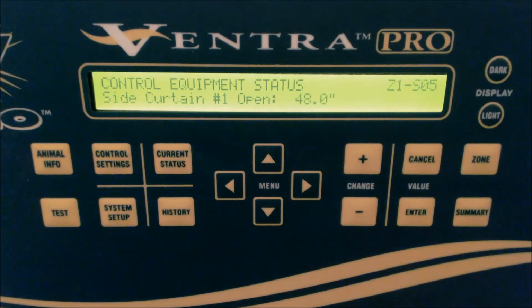The best way to prevent this type of problem is to use a position sensor to help the controller monitor the actual position of the device. Since a lot of operators don't use position sensors, we have added what we are calling a resync feature to help with this type of inlet drifting. This option is available for all inlet types.